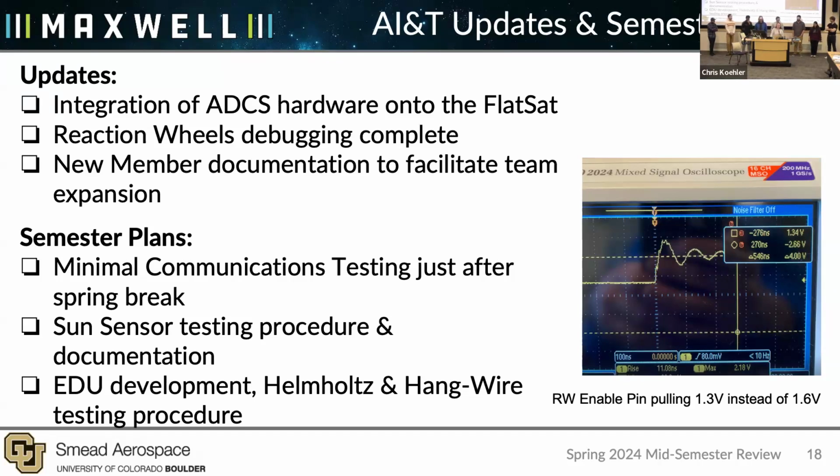On the AIoT side of things, we've been working on integrating all of the ADCS hardware onto our flat sat. So that is our reaction wheels and torque rods. We were plagued for the longest time with an issue with our reaction wheel enable pin not pulling enough voltage. We've pulled a resistor off of that to fix that. We've been revamping our documentation to accommodate new members, getting them up to speed.